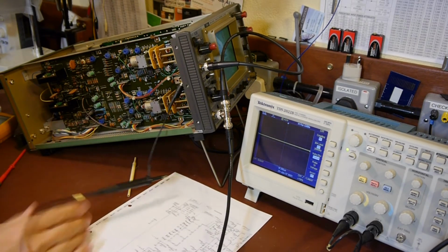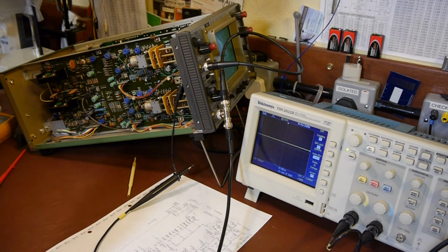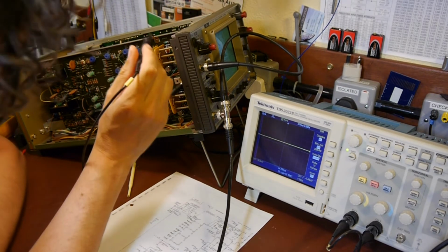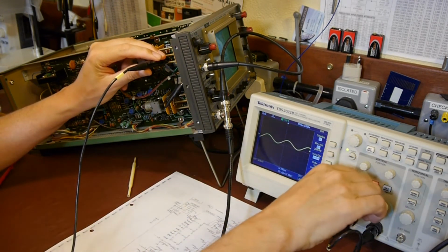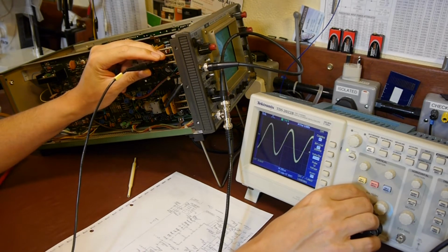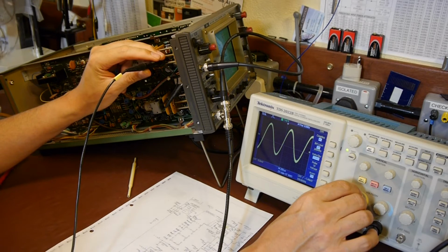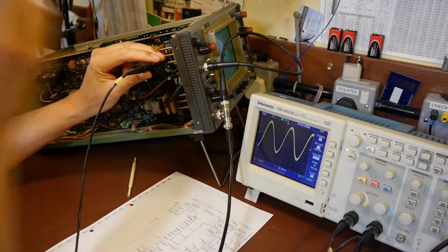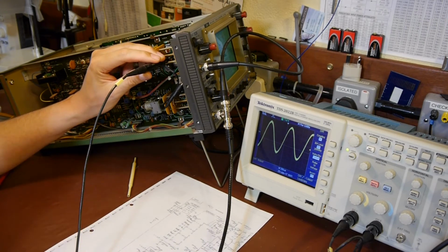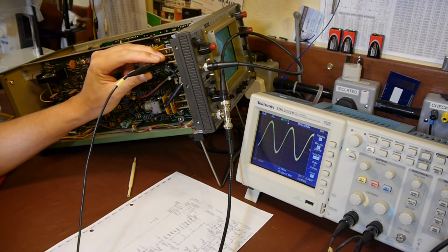Right, so just to recap for my own benefit, we've got 5 volts going in. We've got a divide by 100 stage, so at the output of that we should be expecting 50 millivolts. So let's have a look at channel 1 first, which I think will be there. We have that on 50 millivolts per division, and it's 1 division. Let's increase the... Can we get 5 divisions? We're on 10 millivolts per division now, so we should be expecting 5 divisions on here. 1, 2, 3, 4, 5. Yeah, just over. Got a little bit of noise floating on it, but it's quite a small signal. So, okay, all so far so good for channel 1.